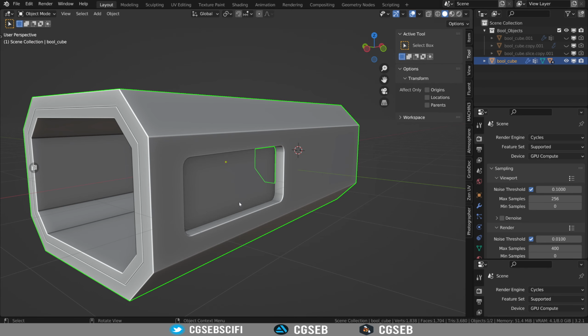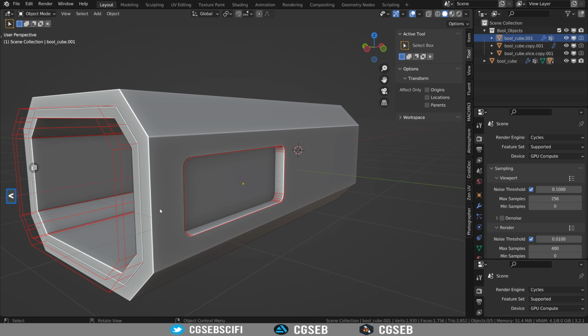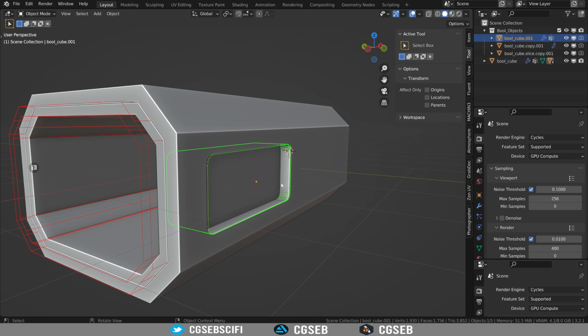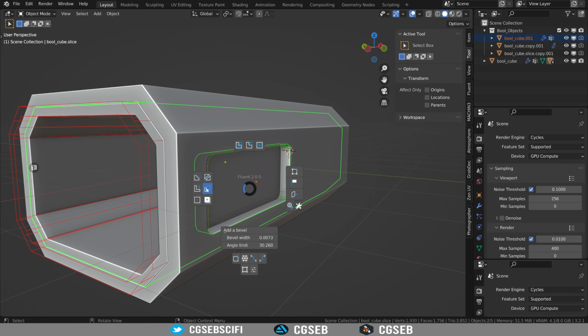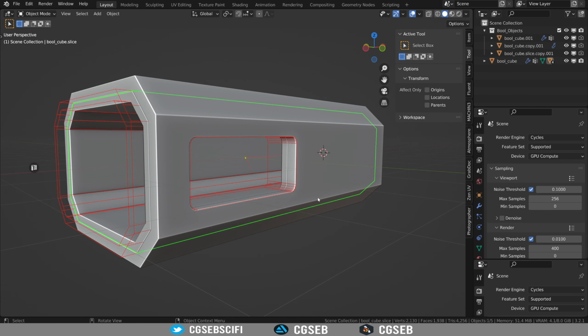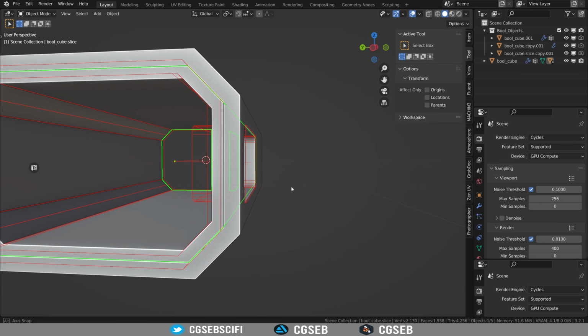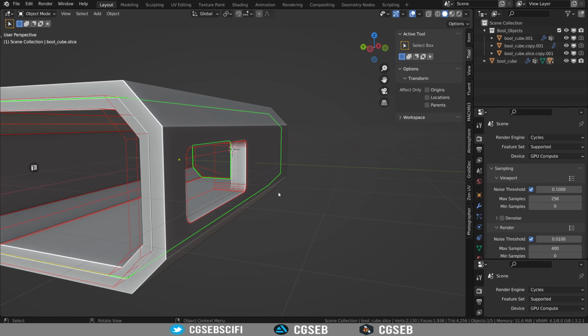Okay, right click, and we are going to show the booleans. So it's the greater than, lower than key, or you can just press F and click on this one. And if we select this boolean, hold Shift, and then click on the inside, we're going to be able to use the difference boolean. Good. We're going to right click and we're pretty much good to go with the window.